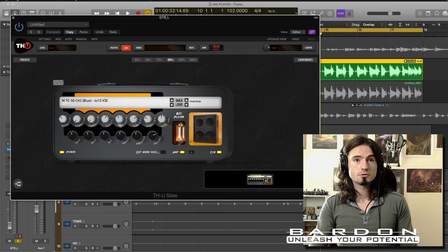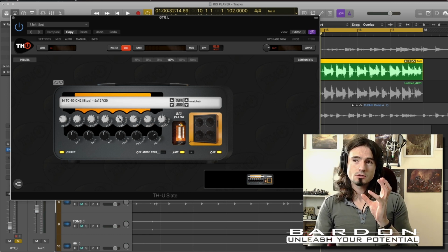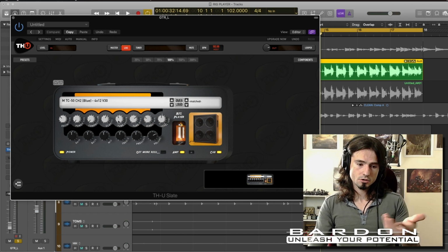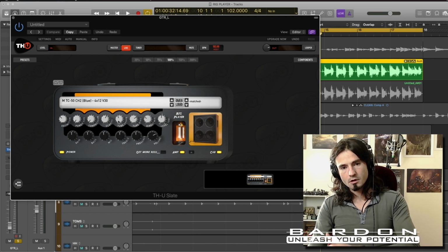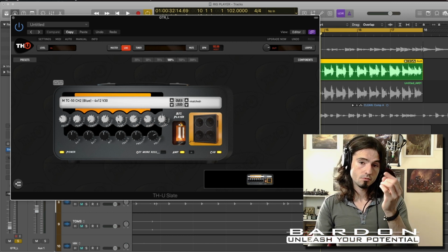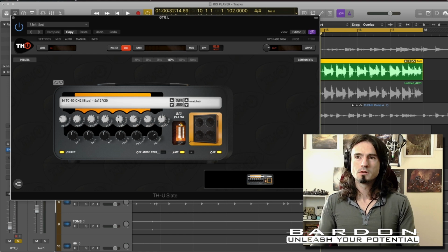And as a result, you get a certain amount of distortion from both of those sections. So this is what we deal with. We're changing with the tube shape the way that our distortion is happening. And we can go from a preamp section distortion to a power amp section distortion sound. The difference is that preamp tends to be a little bit more defined, much more crystalline sounding, and power amp tends to be way more powerful, much more aggressive, but it's a little bit fluffy on the lower end. So here we go.